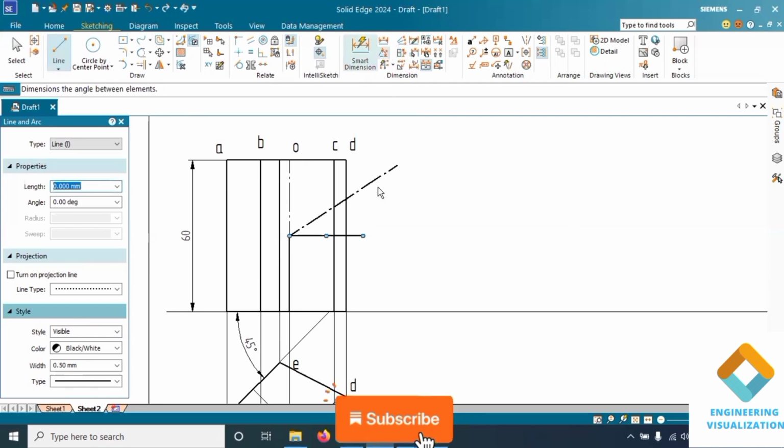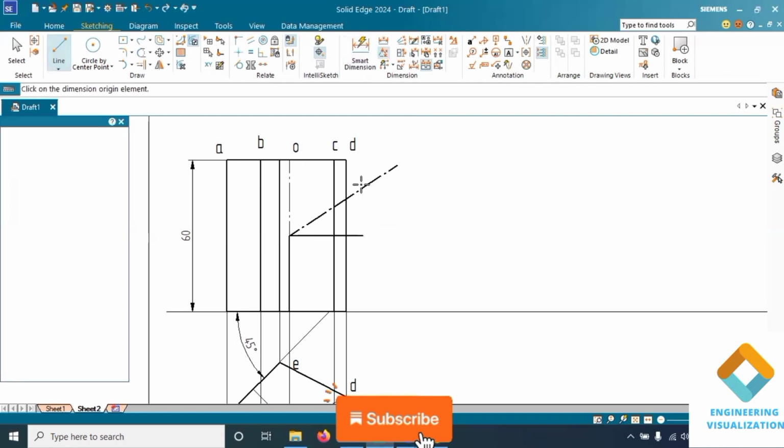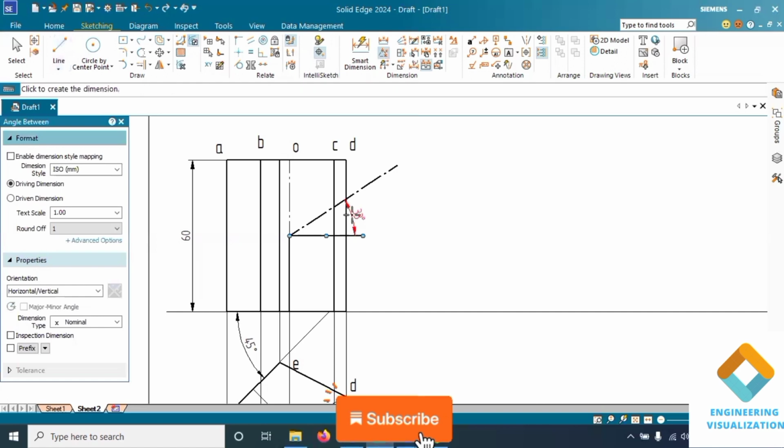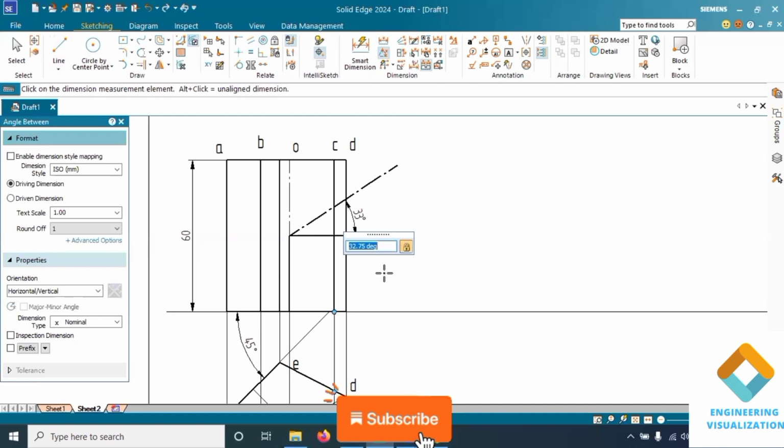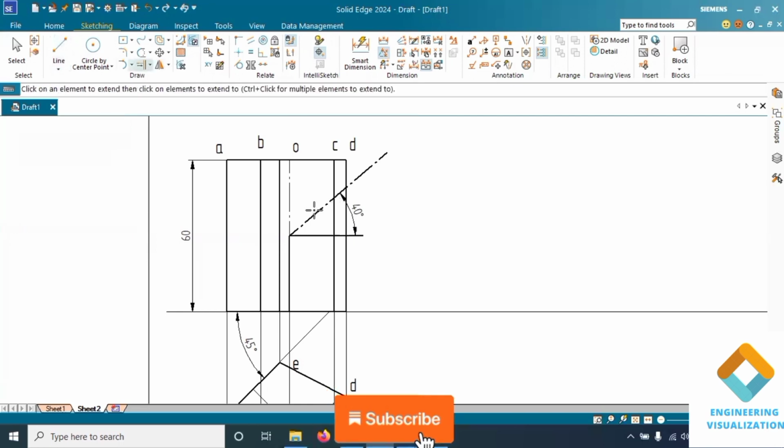Randomly I'll draw a line, then after that I'll change the angle. So this problem, guys, I have not done in development of lateral surface of solid. You can refer to this particular problem, because I have not done this in pentagonal prism, so it can be helpful for you to refer in the exam. So angle of inclination is 40 degree. Now you can extend this section plane. Section plane has been drawn at a height of 30 mm on the axis at an angle of 40 degree.